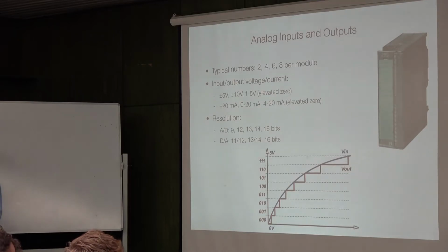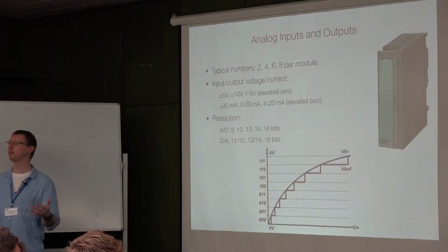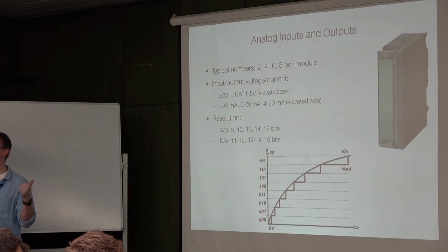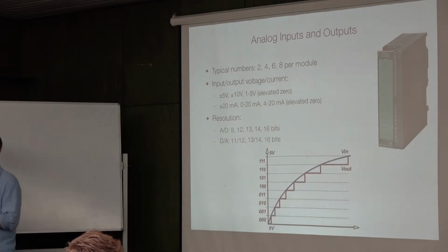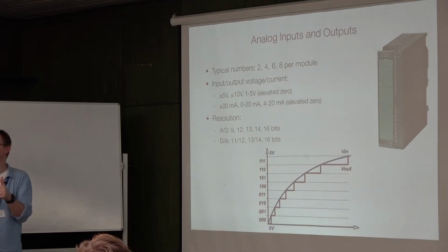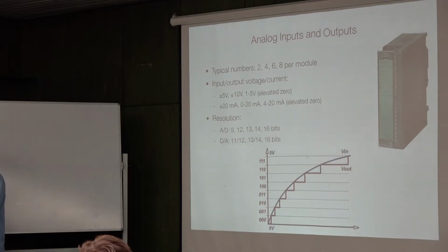And if it is not designed with respect to those quantized inputs, its performance might be bad. Even though you tune everything perfectly on simulations, suddenly you just include quantization and it completely destroys the control performance. So I'm just mentioning these kinds of issues to you, just to know that it's not just about the control design. It's all these little things which then influence both the program complexity but also the quality of the control algorithm.